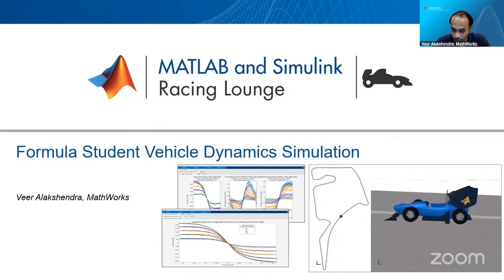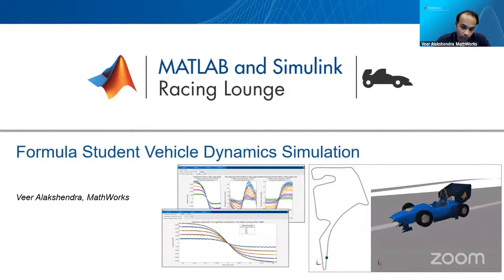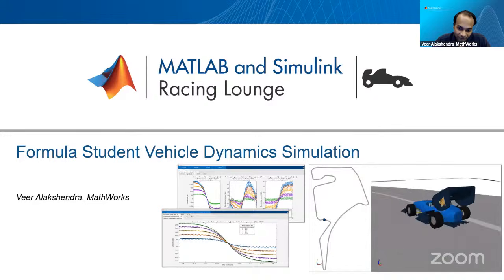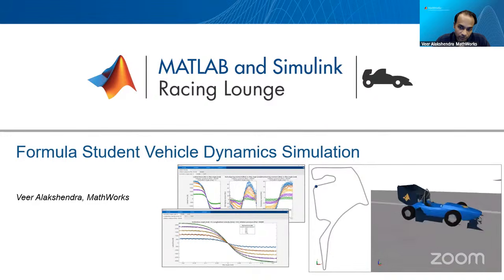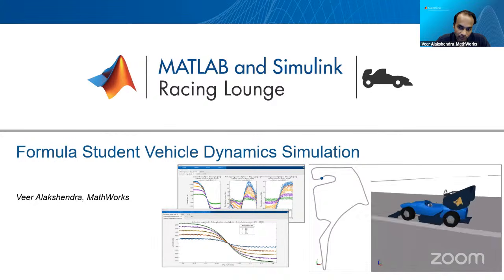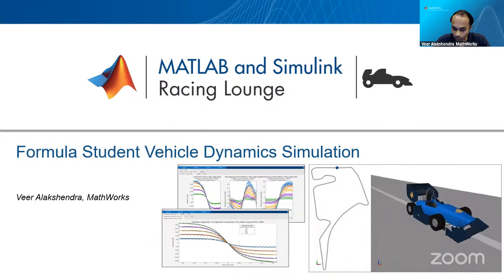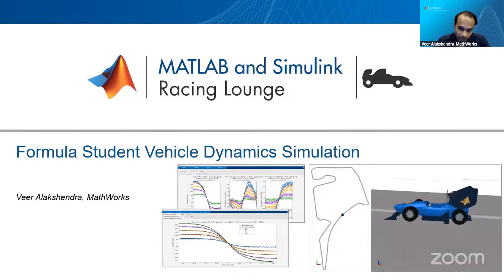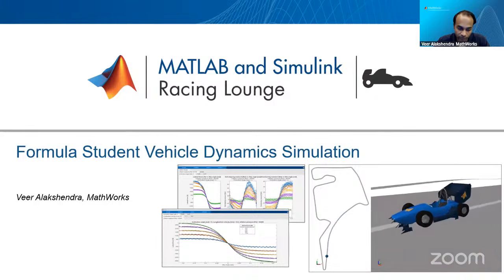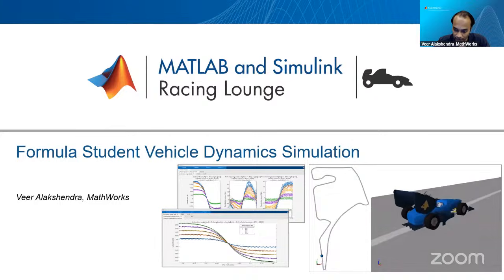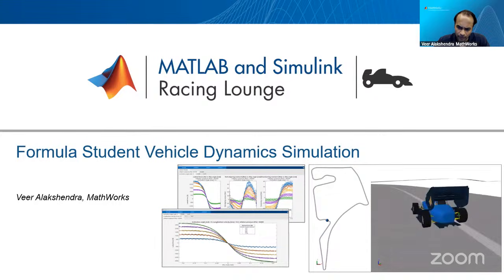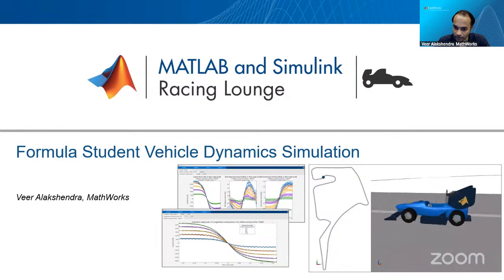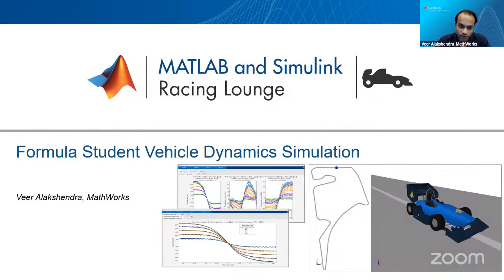We'll be walking you through what the process is, what different toolboxes we are using, and what steps we are following. This time we have tested the script in collaboration with some of the teams who worked with us and tested their TTC tire data to see how the fit comes and how it can be further exported into the .tir format, which is relevant for vehicle dynamic simulations. And then further, we'll go into full vehicle simulation, specifically around vehicle dynamics. We'll talk about the Vehicle Dynamics Blockset, and further we'll go deeper into the Simscape Multibody Formula One vehicle car model. Okay, so let's get started.